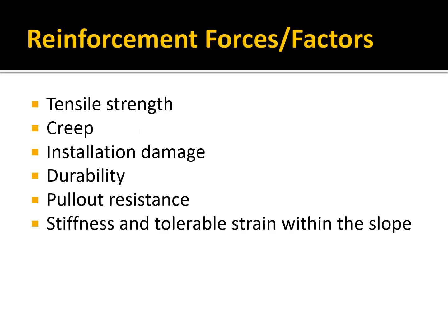So, when you're dealing with reinforcement, there are several factors you need to consider. In a lot of cases, if you have drilled piers or concrete piers or piles, then it might be the shear strength that controls there. But in many cases, like geogrids and reinforced earth walls, it's the tensile strength of the reinforcement that matters. You also have to worry about things like creep. Creep is just a long-term strain that occurs due to sustained loading over time. You have to factor in that there might be installation damage, so include that in your calculations.